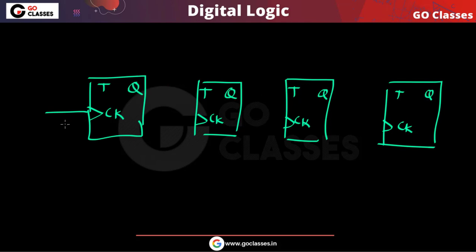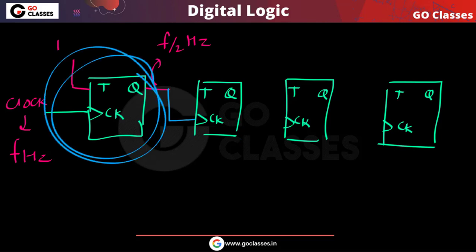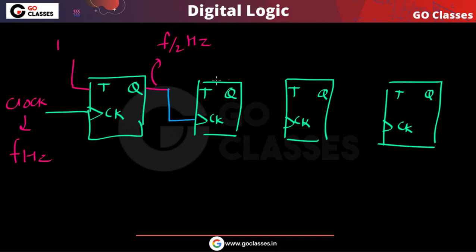Now the idea is this. This is the clock signal that you are applying, and this clock signal has f hertz frequency. Now this output will definitely have f by 2 hertz frequency. Now this output you give as a clock to the next flip-flop. So the output of this flip-flop will work as the clock to the next flip-flop.